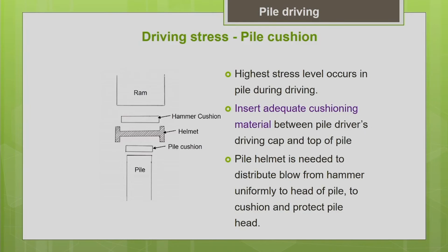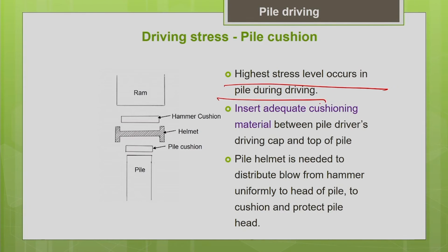Everyone knows that precast piles are likely to be subjected to more stress while driving. They are subjected to more handling stresses, and when you drive the pile into the ground, they are subjected to more driving stresses. That is why all these stresses should be taken into account when you design your pile. The highest stress occurs in the pile mainly during its driving, compared to during its service life.